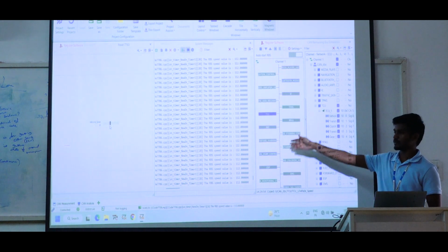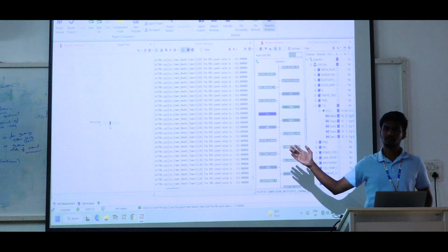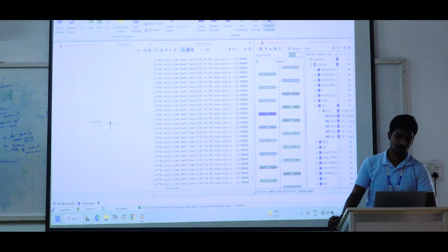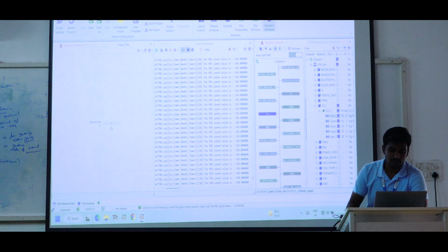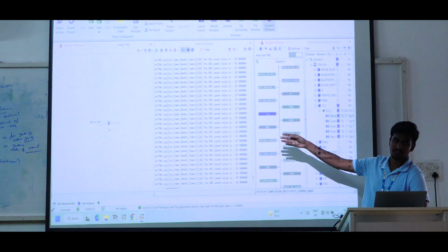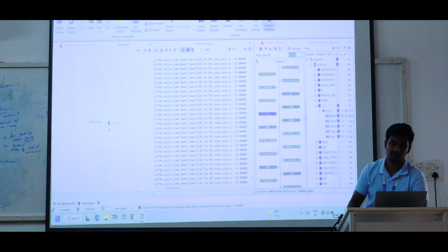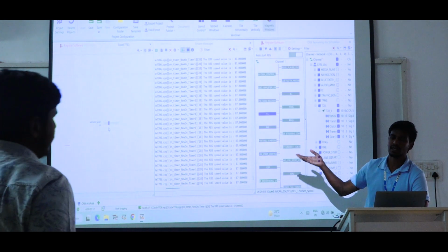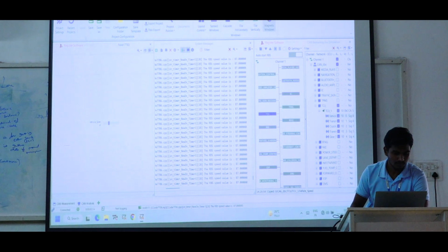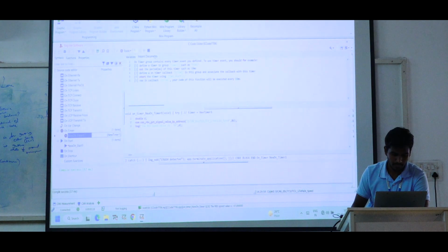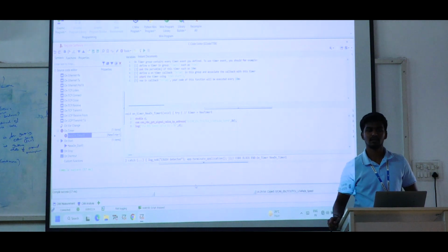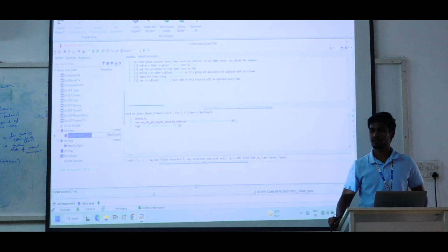Based on this value, the vehicle speed will be increased. Based on that, we are going to work with it, get the distance values, get the seatbelt values, whether it is enabled or not. It is one kind of value transmission that you are able to see by CAPL scripting. This log is not necessary; for our understanding purpose I am putting the log, otherwise we directly write the code. Open the scripting. Stop the scripting. So now we understood how to get the signal by RBS with the help of get signal value address.